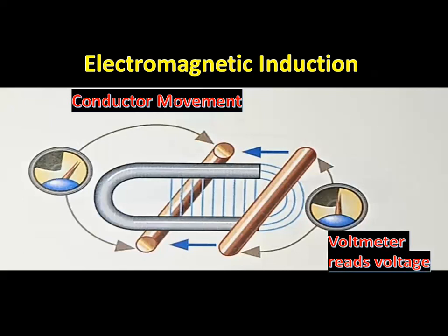In an alternator, the revolving magnetic field of the rotor cuts across the stator windings and induces voltage in these windings. This voltage supplies current to the battery and electrical accessories in the vehicle. In an ignition coil, the windings are stationary and the magnetic field moves across these windings to induce voltage in the windings. This voltage is used to fire the spark plugs.